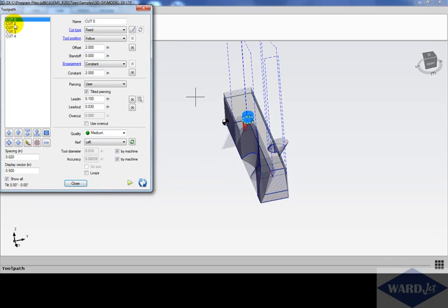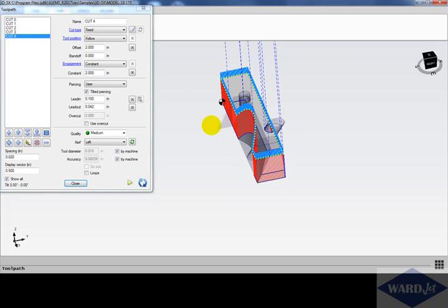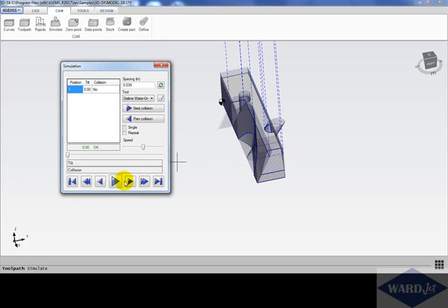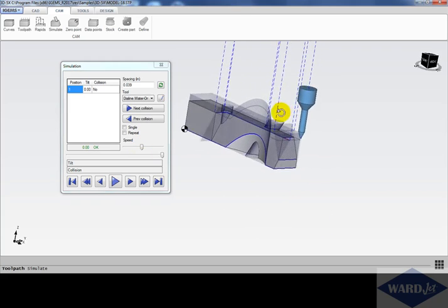So I think that covers it. We got that cut, that, and then we've got the end cuts. We've got that bevel cut there, and then the outside cut. And we can do a preview on that last one. We can use this little slider here if we want to speed it up, slow it down. And that should give us everything we need.